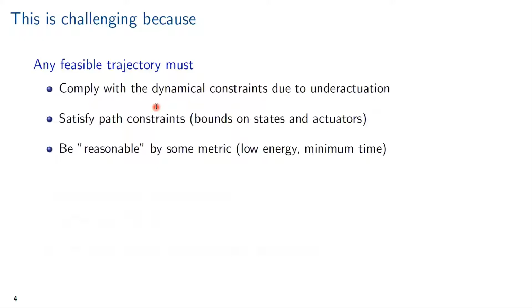Now, this means that what we can make the system do, the motions, is limited by this underactuation. For example, if you're out for a walk, try stopping in the middle of a step. It's more or less impossible. And this is why, when you have a walking robot with underactuation, it's what's called dynamic walking, or basically controlled falling. So the robot keeps falling forward, but we use our controllers or our motors to compensate for it and make this controlled falling into a walking gait.